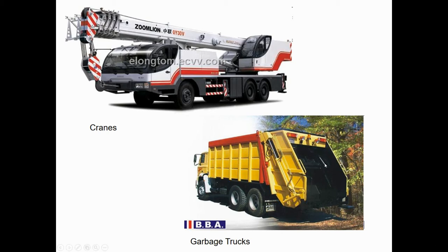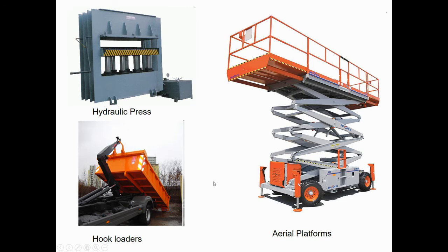We need to have power to move this piston and achieve very high pressure to have a higher force to compact the garbage. Same thing here in the hydraulic press. We are going to have the hydraulic tank, and this hydraulic tank is going to have a pump somewhere here, and this pump needs to connect of course to a motor by rotating the driving gear, and the process will happen. We're going to pressurize the pressure inside the cylinders and the piston, and boom, we're going to have the magnified power to force to compact the thing.